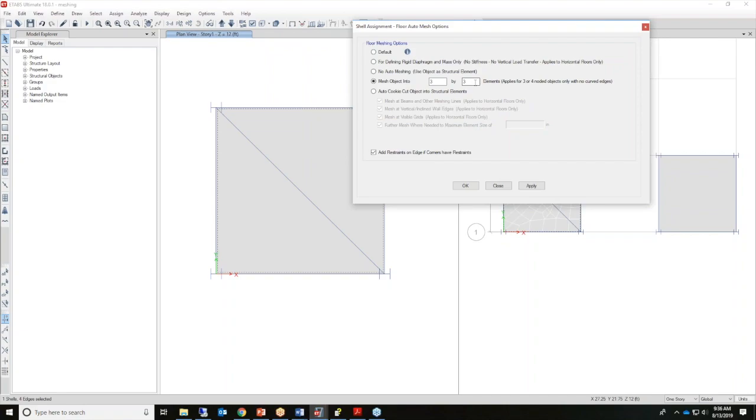And I understand that errors with these sometimes aren't easily resolved. It may require making a much more coarse mesh, because sometimes if the mesh is too dense, it gets really tight, especially in those corners where you have angles less than 90 degrees. I recommend making this maximum element size larger, so you're not getting those tiny, tiny triangular mesh element shapes that sometimes cause instabilities.